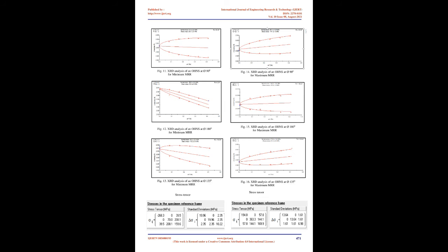To obtain the surface finish of 0.35 to 0.36 µm, the work speed can be kept in the range of 300 to 350 rpm with 6 number of passes and feed of 2 m/min. The MRR can be obtained in the range of 0.30 to 0.32 gms/sec for the above parameters. The residual stress results for surface roughness and MRR show that as the speed increases the compressive residual stresses are developed in specimen for obtaining surface roughness in range of 0.35 to 0.36 µm. As the metal removal rate increases for 0.2 to 0.3 gms/sec, tensile stresses are developed.